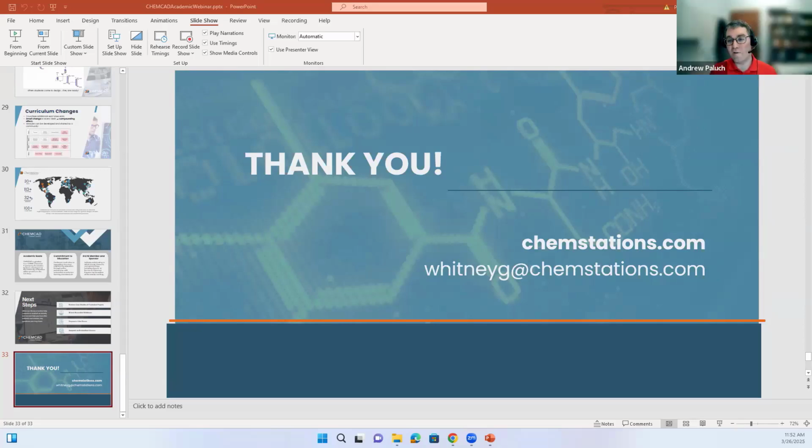I haven't directly modeled a fermentation process in ChemCAD. So the question would be whether you have any sort of kinetic data. I'm trying to think more in general, and it depends on the level of detail. If I'm just interested in some steady state equilibrium process, and you have equilibrium data for that fermentation process, then you could definitely model it in ChemCAD. If you had kinetic data, you could do that as well, and then you could get dynamic data as well.